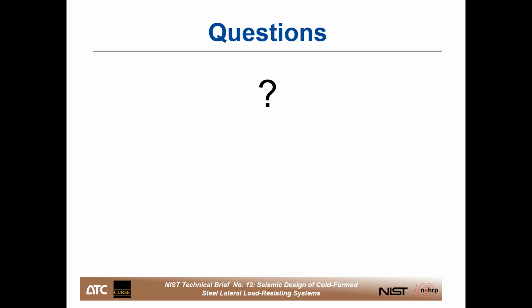If somebody asks, gee, is it possible to maybe develop or design a hold down that could dissipate energy? I'd say sure. Yeah, there's probably ways to do that, right? You could design some sort of a yielding mechanism in a hold down that could work. But you want to be super careful, right? Because you absolutely positively do not want that hold down to disengage. I mean, that is a critical part that's resisting overturning forces. So you'd want to tread very cautiously on any path that led you towards using that to dissipate energy.